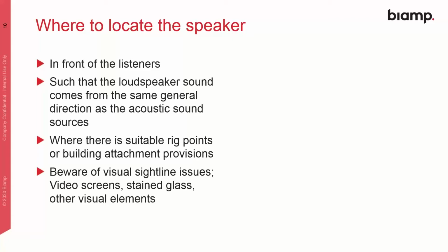Where to locate the speaker? Well, obviously in front of the listeners. Locate the speaker such that the sound comes from the same general direction as the acoustic sources that you see on the stage. You don't want to see someone up there talking and hear them from somewhere around behind your head. So that's sort of basic, but some people forget it.